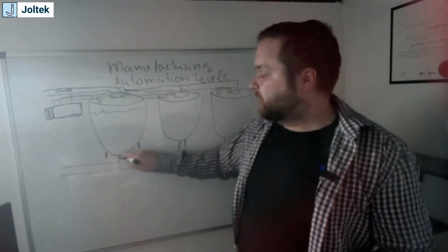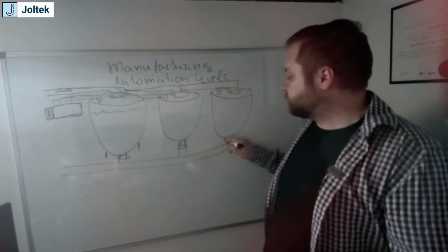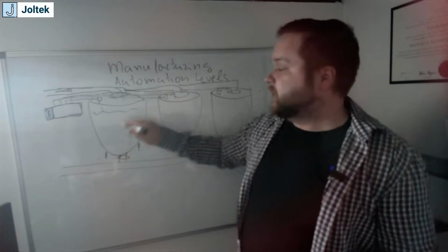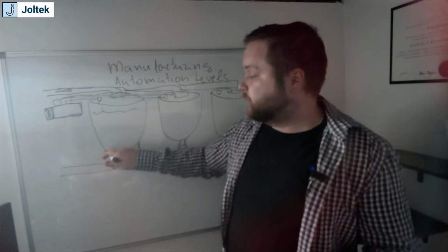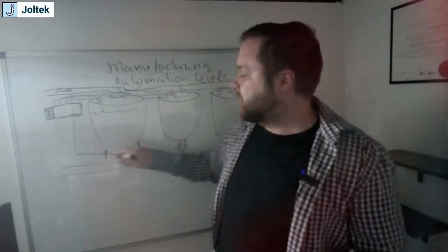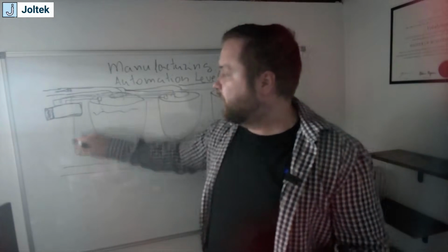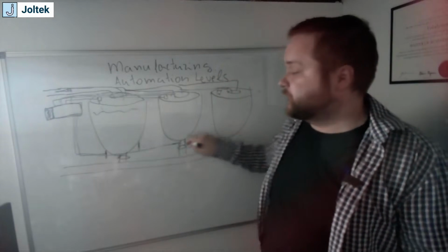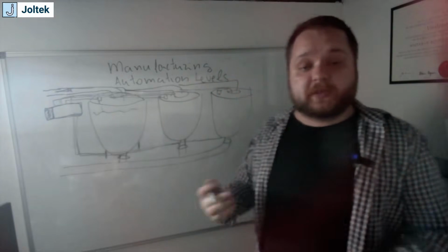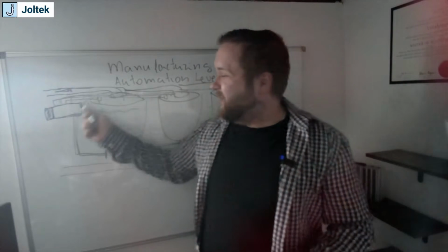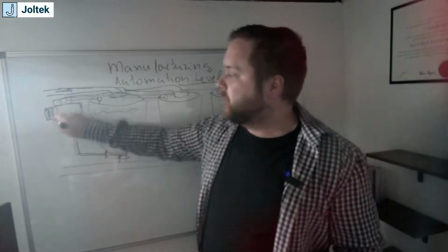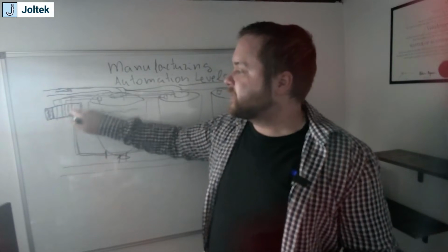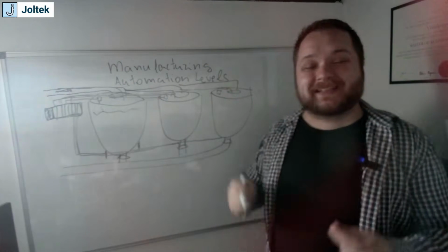You probably have, like I said, a discharge valve here at the bottom of the tank. You're going to have a load cell. Again, the load cell could be analog, so it could come in as an input on the 4 to 20 milliamps. It could be a voltage as well, but it could also be on the network. So let's talk first of all about the current system, right? Now we've introduced IO. And so at this point, your system becomes a little bit more complex than in the previous example.